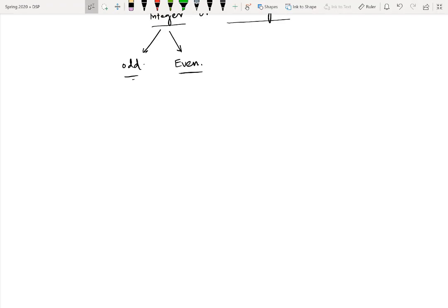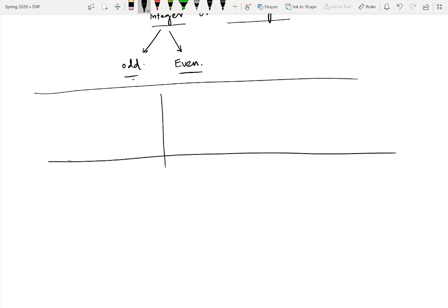To have that criteria, let's say there is a passband signal whose spectrum is like this, with the bandwidth of capital B. This point is FL, this point is FH, and similarly the same thing on the right side. And just to see the difference, we can consider the opposite copies. It is minus FH and it is minus FL, right?